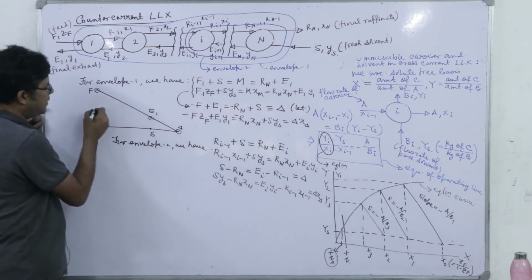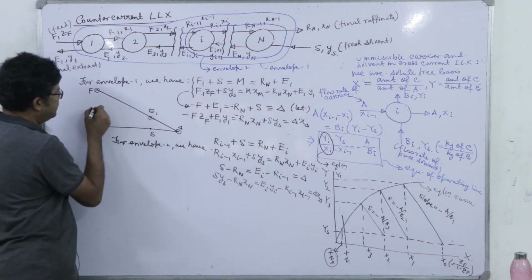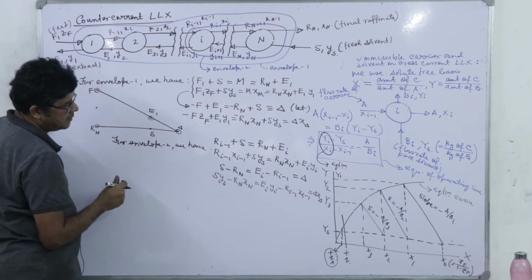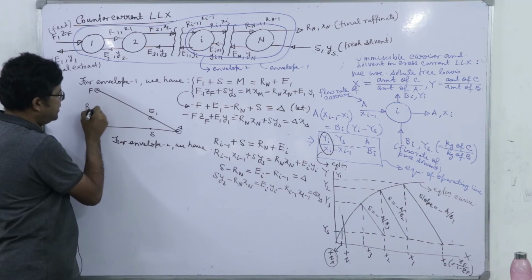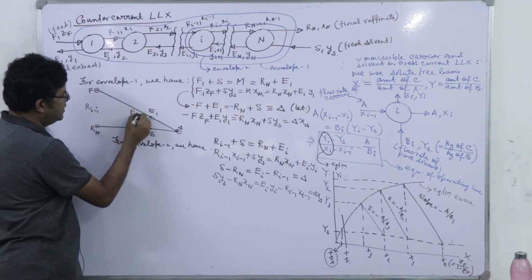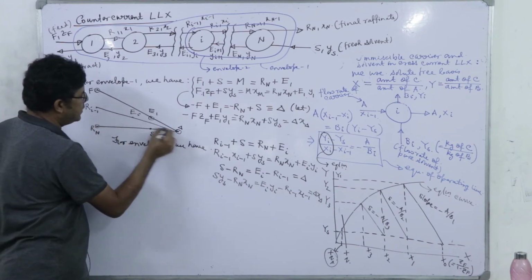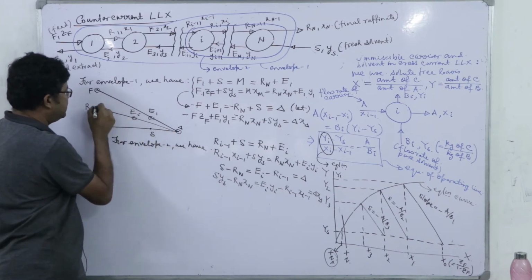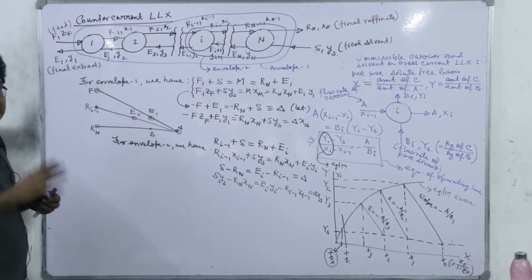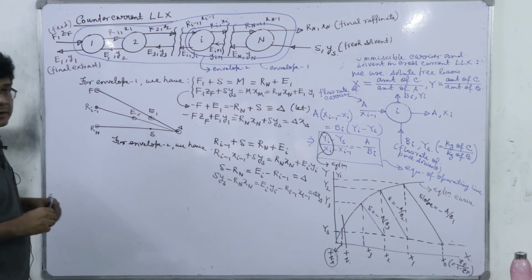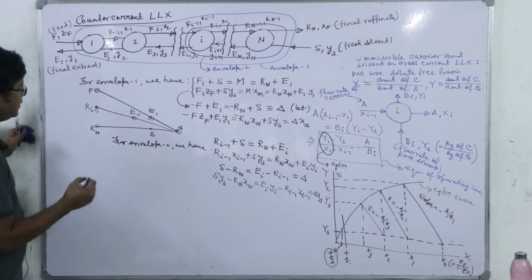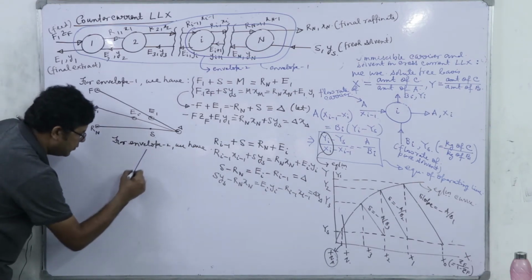So we can think of another point which is Ri minus 1, here it will be Ei, and this if we connect and extend, right, they must meet at point delta, and that gives you the idea of how to calculate the number of stages in case of countercurrent liquid-liquid extraction. See what we are doing.